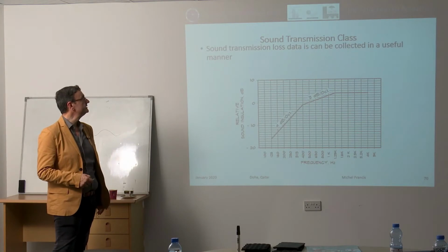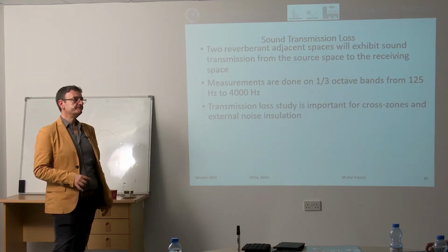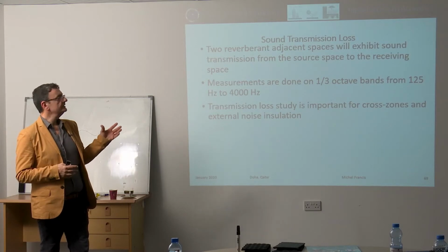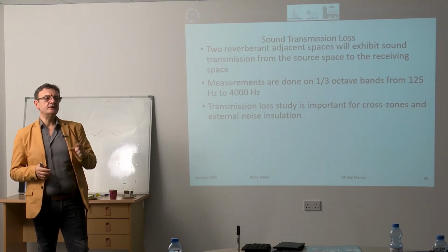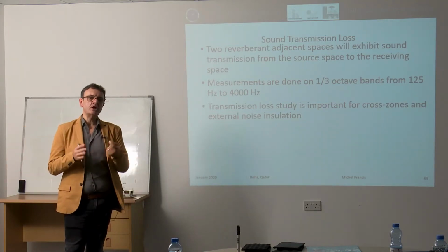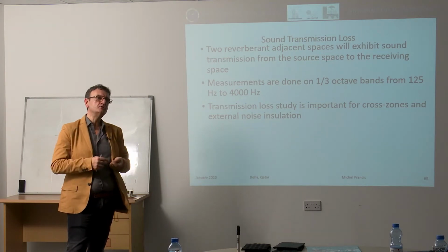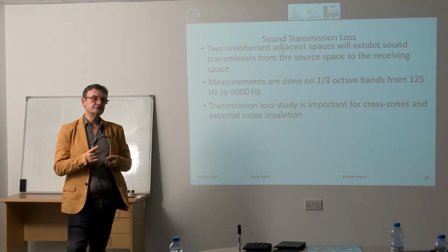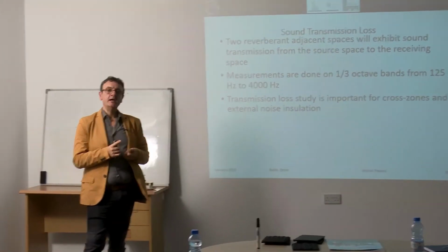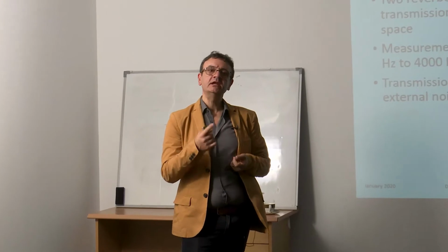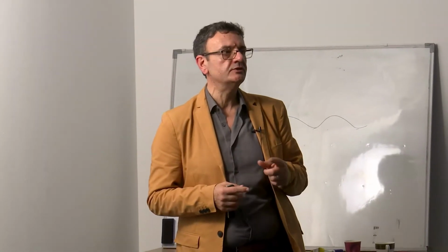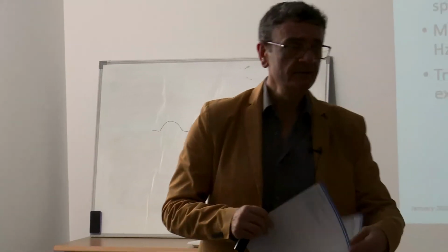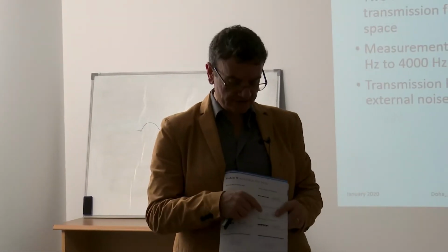So I'm going to repeat a little bit. The sound transmission class is related to sound transmission loss, and that's a one number measurement for a material to tell you how many decibels that material is going to reduce the noise when that noise is going to pass through it. Always remember that there is flanking noise, and that is also something you must remember when you talk to consultants. So if they tell you in real life there is a difference between what you're doing and what we have in real life, you tell them this STC is under strict lab conditions. That's the number, STC here.